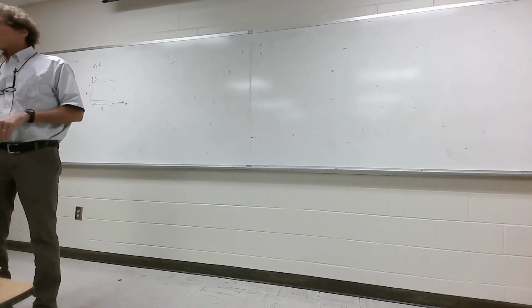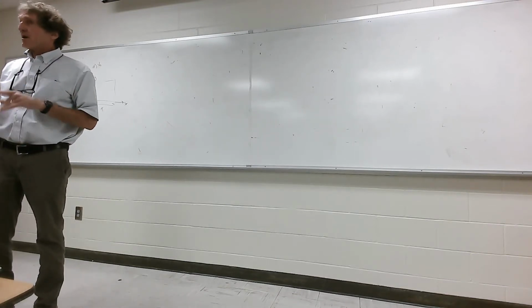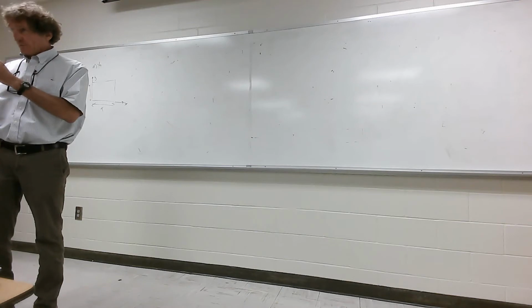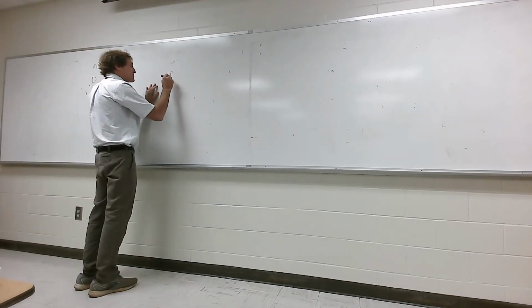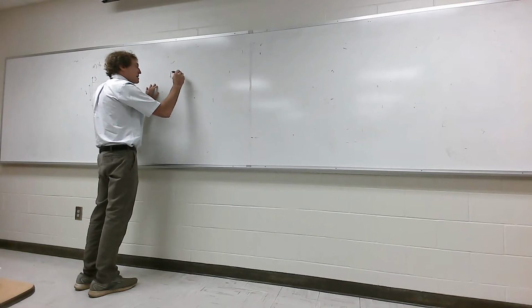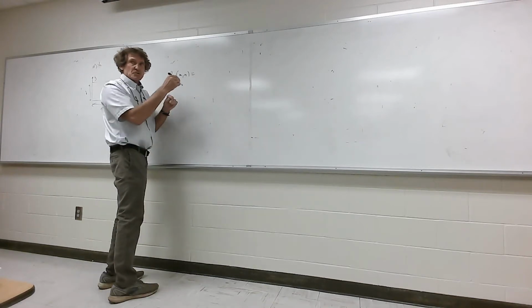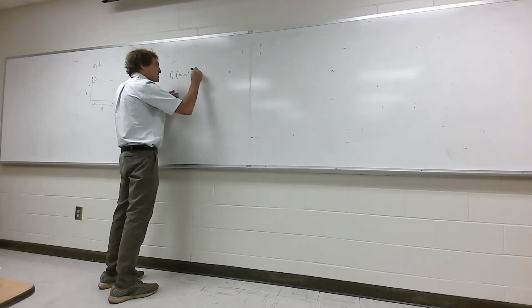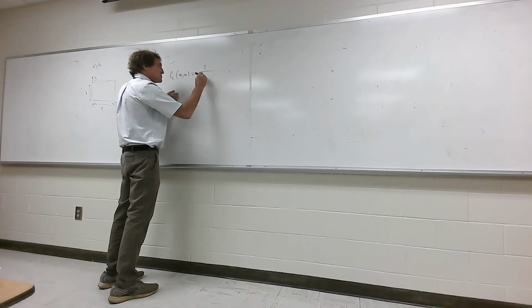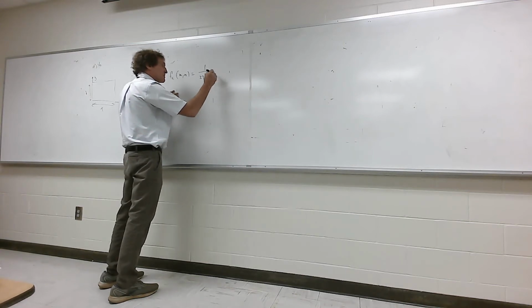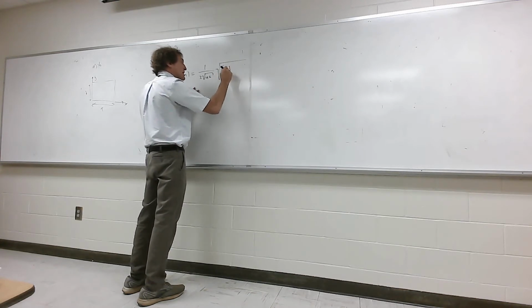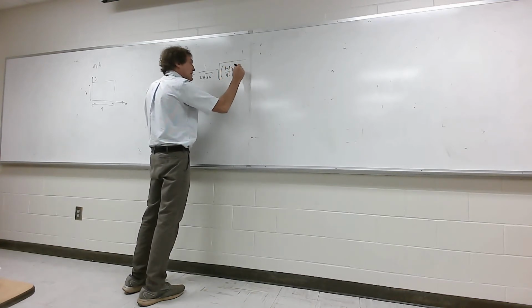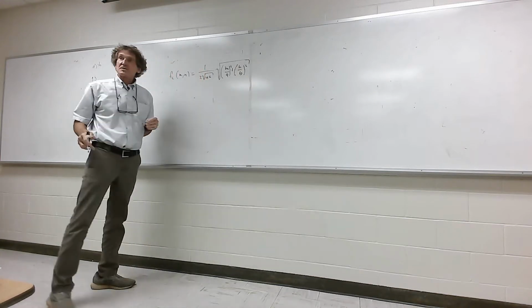Now this is fundamental, it's important. The lowest order mode a rectangular waveguide operates in is the 1-0 mode. Do y'all follow me? Now listen, when you're calculating the modes, you don't have to assume 0. You can put fc = 1/2 square root of mu epsilon, times square root of (m over a) squared plus (n over b) squared. Now that covers all the possible modes.